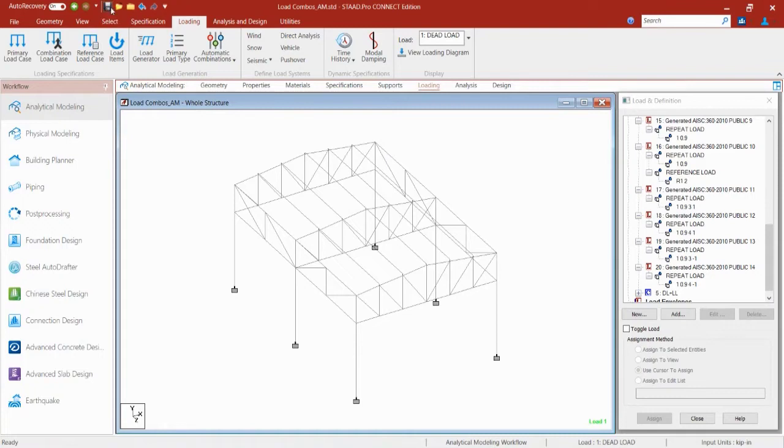Now, whenever we generate load combinations in STAAD.Pro, we're basically utilizing some of the load combination generators that are typically installed with the program. And you saw when I used that command for creating load combinations that I did select a code and a category. I get a lot of questions about how I know what is going to be generated for each one of those. So within STAAD.Pro, you are able to preview and edit or create your own load combination generators.